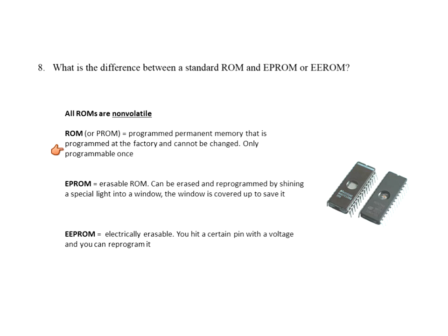Now, to make ROM a little bit easier to handle for smaller companies, they've actually come up with two other types of ROM. EPROM is an erasable ROM, and it's identified by this little window here in the chip. Usually this window is covered up with a piece of paper. If I have a piece of paper over top of that, that chip will never be erased. So once I program it, it'll remain acting like a ROM. But if I peel this piece of paper or cover off of there and shine a certain kind of light in there, I can reprogram it. It's said to be erasable.